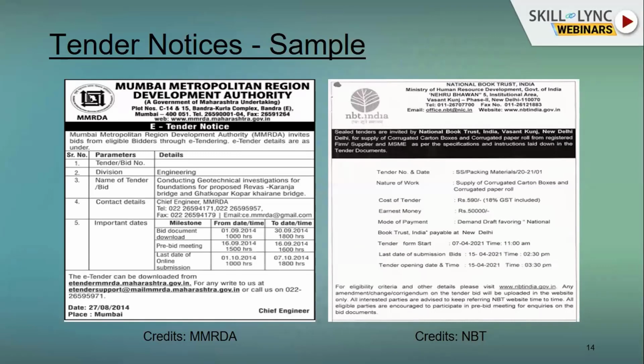But to arrive at this, the contract manager has to do multiple tasks, starting with preparation of drawings and specification, arriving at the cost, the total project cost, and he has to target a feasible deadline. We cannot say I have to construct a G plus 40 building in 1 year. He cannot mention 12 months here. Realistic timelines have to be put. Otherwise, no contractor will quote for this, because everyone knows there is compensation for the delay and no one will accept it.